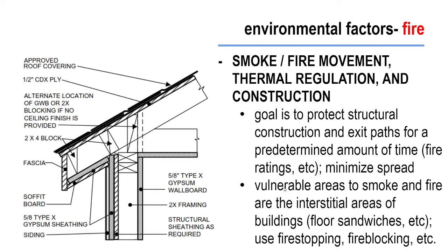Whenever we do have those protections in place, the walls will be rated for how many hours they can stand before they become structurally compromised. So this wall here is rated for 1 hour, so it can stay and be okay for 1 hour of exposure. And there will be different doors also, and they are rated as well.